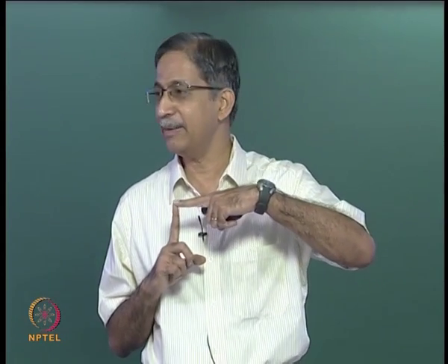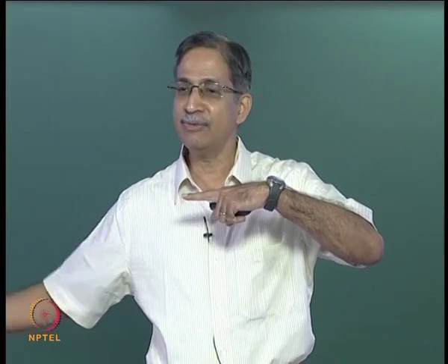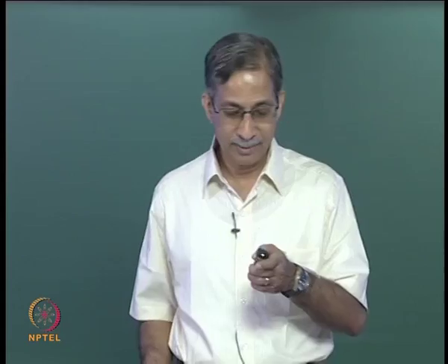When the child is loaded, you will get something in the parent, let that be very clear, right. So you can quietly remove the child from the picture and look at the parent. Parent is a cantilever. Now if you apply a moment at joint B in that L-shaped cantilever, do you think anything will go into element 2 and 3? No. So this is the flexibility method. You really have to enjoy the physics of the problem and get the answer. So you just have to draw this.